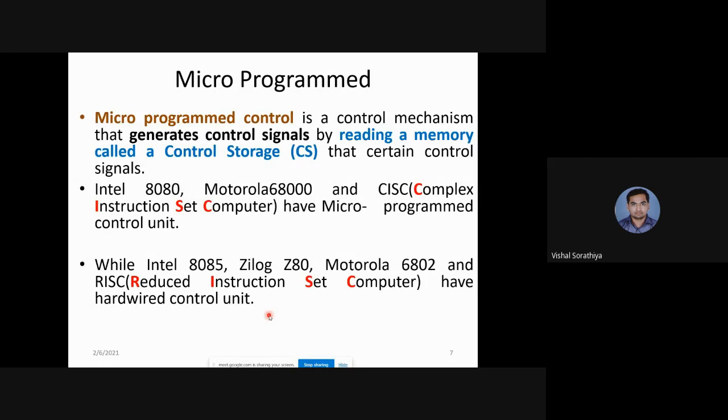You don't have to do video streaming with a washing machine, you don't have to access the internet, or you can say you don't have that much general purpose application. At that time you are not going to spend money on such a costlier processor. You need to find some reduced or limited functionality device or architecture. So these are the two things. Somebody will ask the question of where the microprogram control is used and where the hardware control is used, so this should be differentiated.